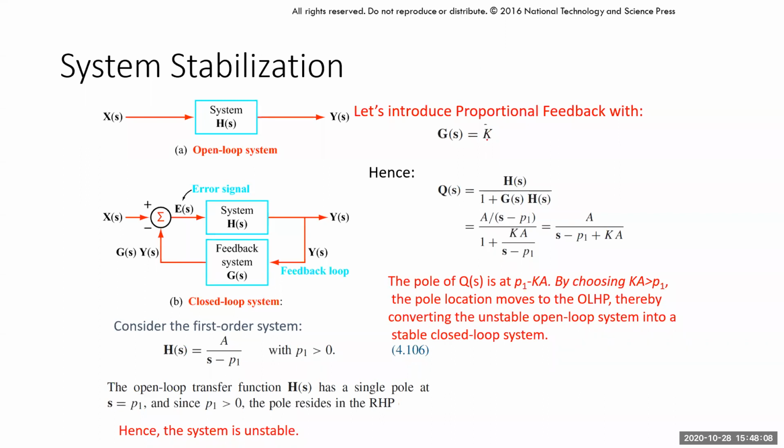And there's various names for feedback. K is proportional and it's just gain, like the resistors. But you can also have something called derivative feedback, where you put an op-amp circuit in between that takes the derivative. You can have integrative feedback, where you put an integrator in the feedback loop, which is what we've done with the DF2 filters.